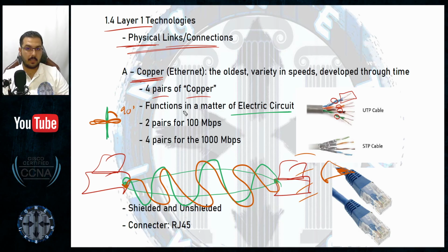In that case, using that solution, we will eliminate, seriously, not reduce, but eliminate the noise field of the magnetic field. So we will kill the magnetic field noise, because it will be twisted. It will no longer be at 90 degrees perpendicular to it, so it will not affect it anymore, and you'll have your pure electric field working. That's why they are twisted pairs. So they look like twisted pairs.